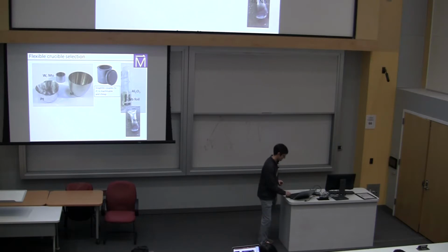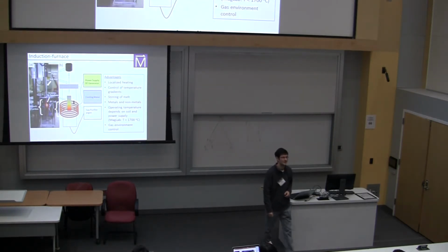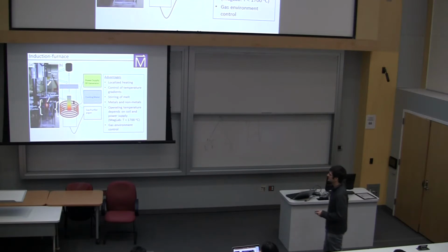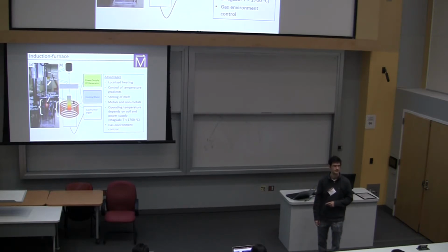Well, okay, right. This was something that I thought would be a problem in a system such as this. But look, in this apparatus where we do have a quartz tube, it turns out that the radiative heating coming off of the sample at 1700 degrees C, where the distance between the workpiece and the quartz is only something like this, the quartz, which is water cooled to a certain extent, reaches nowhere near the melting temperature. So if you set up something like this where you focus your heat, the heat is really focused on the sample and not on the surroundings, you can reach very high temperatures in the tantalum tube.